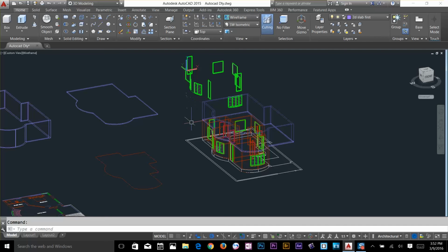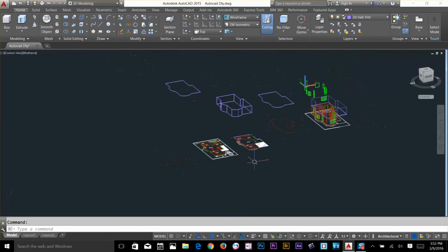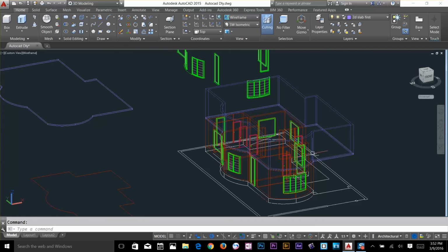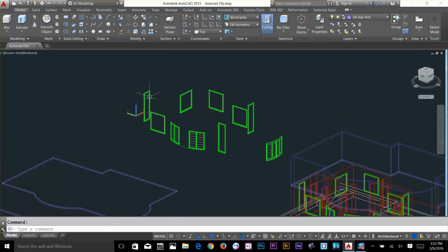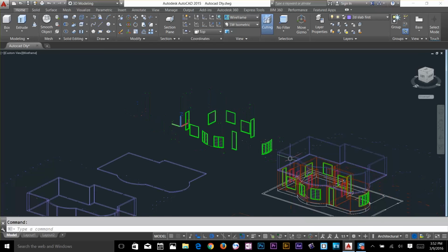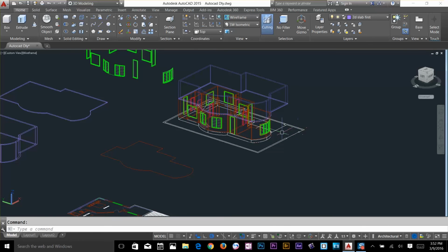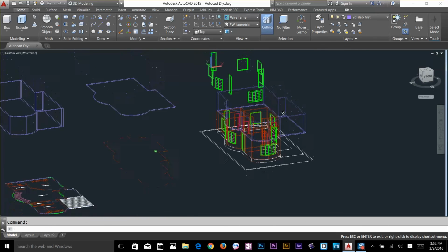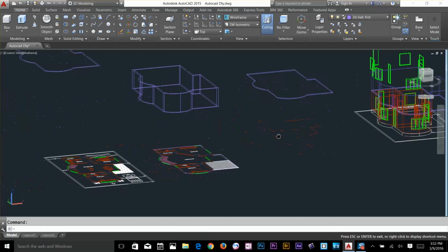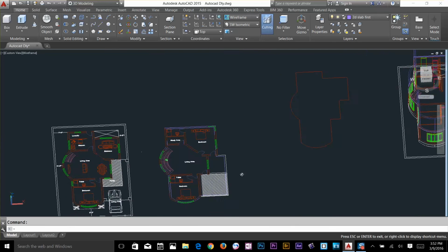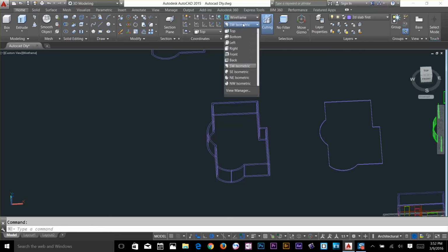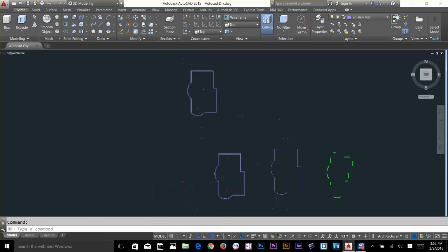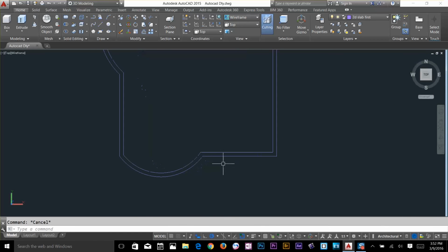So first we're going to cut the edges for the windows. So how can I do that? For that, it's good practice that you keep your windows for your later use. Let's say you had a cutting from the bottom, so you can do that on the top as well. So now let's do one more thing here. I go back to that viewport, go back to your top, and then make another polyline here.